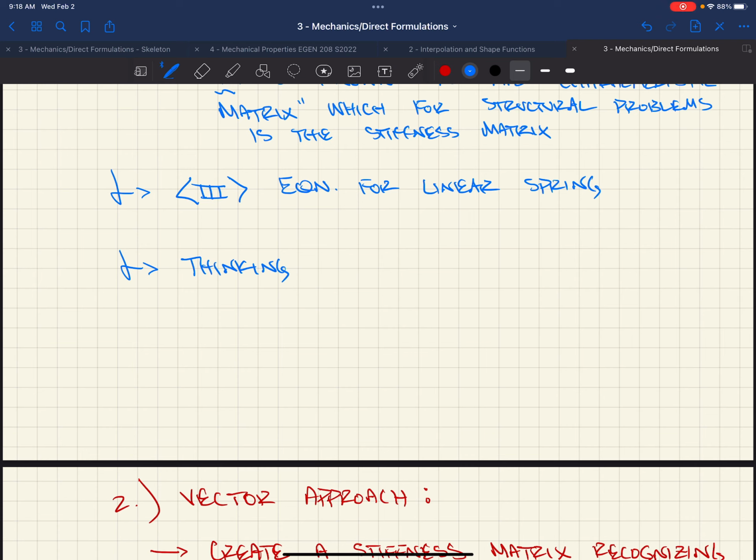So when you're modeling, it's always good to think of things with respect to stiffness, and your model is driven by stiffness. If things aren't looking right, or the behavior or displaced shape doesn't seem right, think of it from a stiffness perspective and where loading might be going.